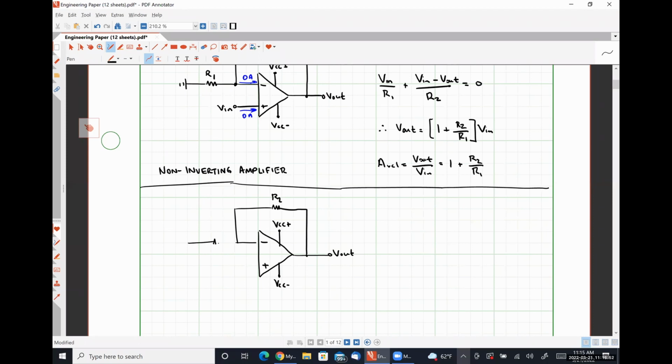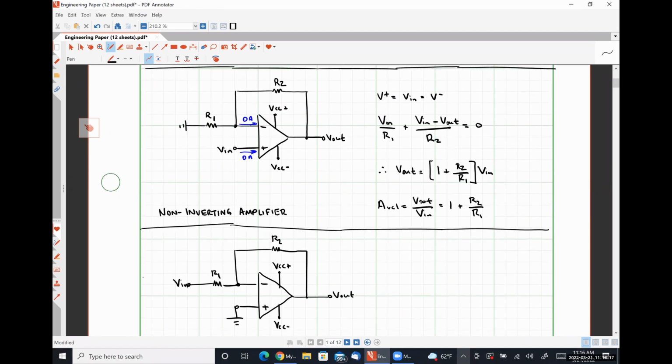We're going to have that exact same resistor R1, but now we're going to apply our input signal at that open leg of R1, and we are going to ground our non-inverting input terminal. So let me scroll up here just real quick. The fundamental difference between these two circuits is that we are taking these two voltages and swapping. Otherwise, they are completely and utterly identical.